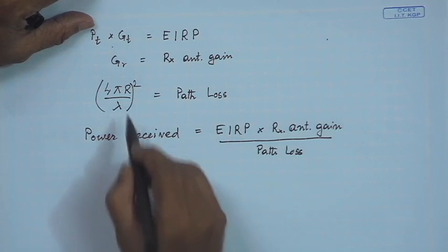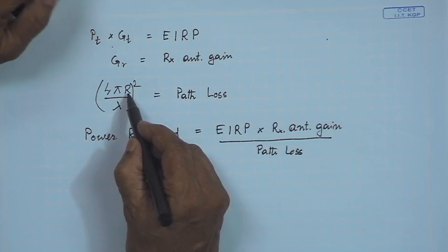So, from the ITU point of view or availability of spectrum point of view, it is preferred to go to higher band, so that we can increase the capacity, more users can come, larger bandwidth is available. But there is a problem that your path loss will be more. Therefore, assuming the R is same, that is you are working at geostationary satellite, path loss at higher spectrum will be more. So, therefore, the antenna gain has to be increased. We will see all those things in detailed calculation when we do.